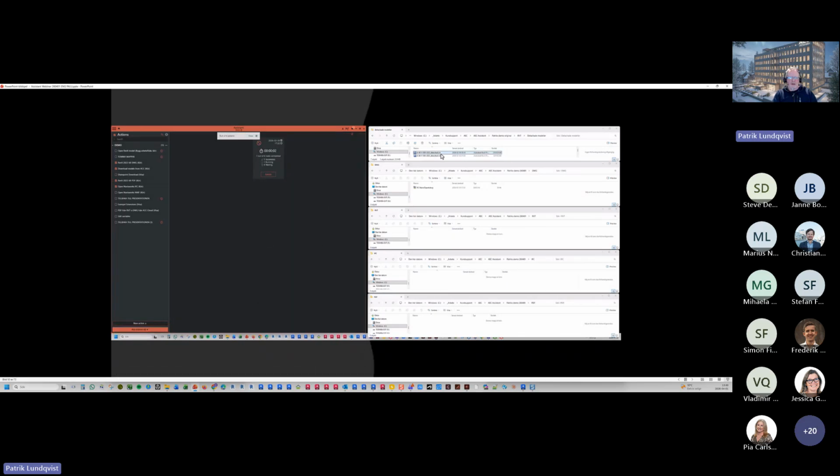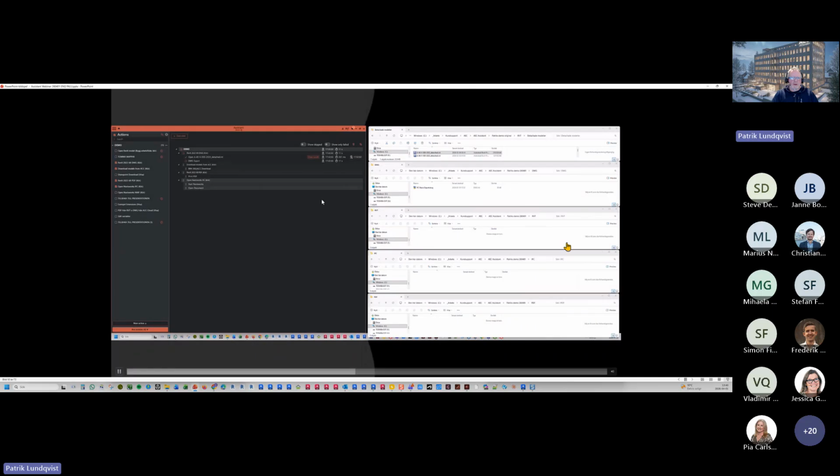If you work with Navisworks, you know that you open up a federated model and it automatically uploads the latest IFCs. So as long as I've copied the latest IFCs from Construction Cloud down to a folder and open Navis as the last thing, it's going to open with the latest. You can see here, I've now clicked play and it's started to run. So I can see here in real time, 27 seconds.